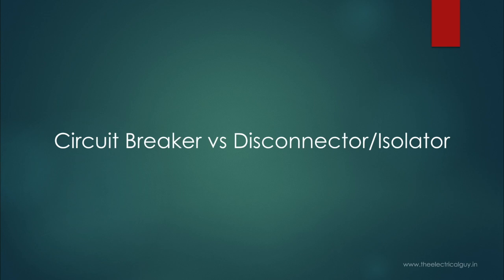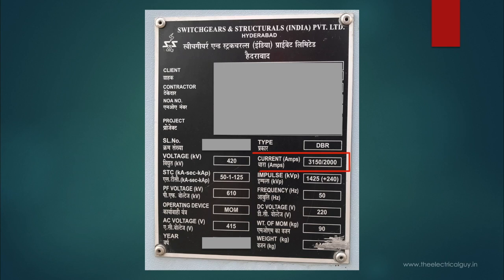So moving on to the nameplate. So next thing is a rated current. So here you can see this particular disconnector is designed for a rated current of 3150 ampere or 2000 ampere. So impulse we already saw. Next is the rated frequency. So this indicates the rated frequency for which this disconnector is designed. So as it is designed for India, it is 50 Hz.